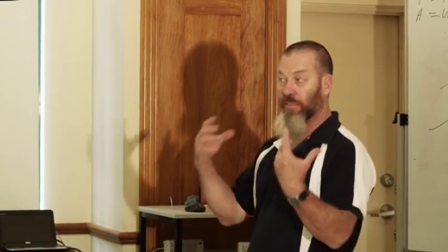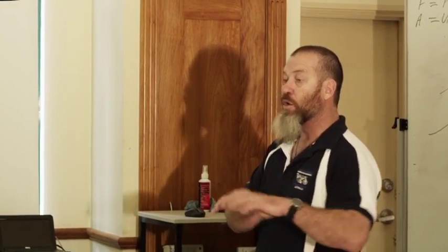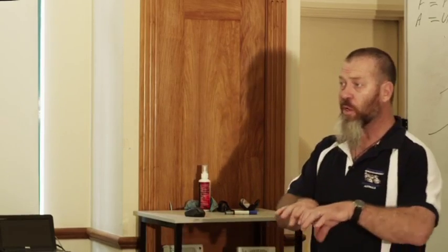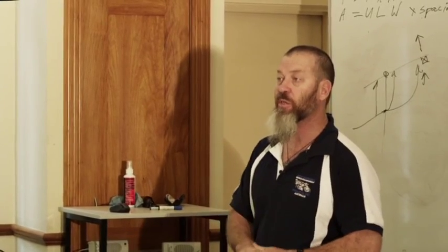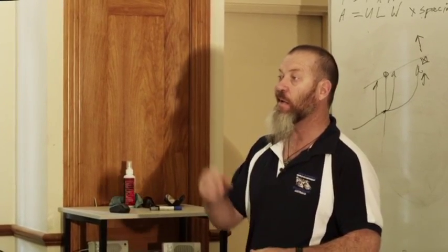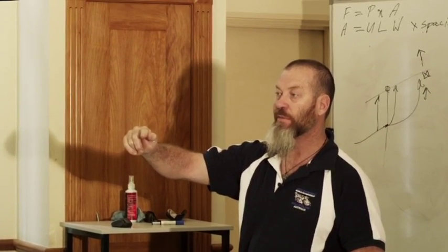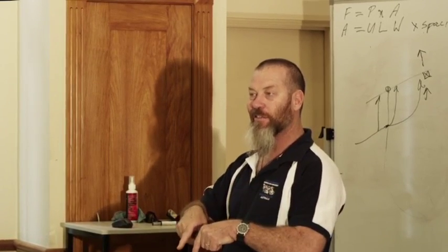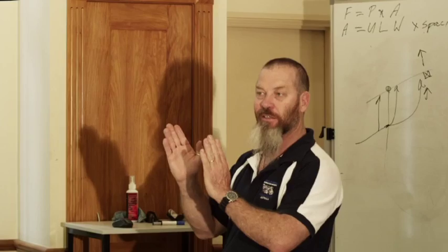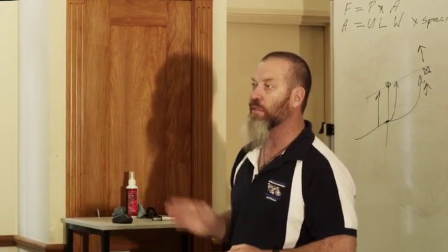That's what we're going to do for Task 57 because, as I said to you earlier, I want you to be efficient. So where your bottom plate's fully supported by a concrete slab or solid blocking, 35mm bottom plates. So again, we're not saving 1 row of top plates, we're saving 2 rows of top plates. Okay, so if it was a 2-storey building, downstairs, because your floor joists are at 450 centres, you have your studs to suit your floor joists. So they're directly underneath all your floor joists.